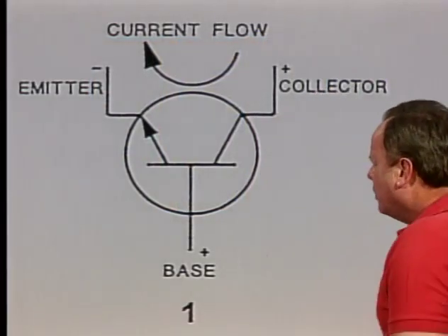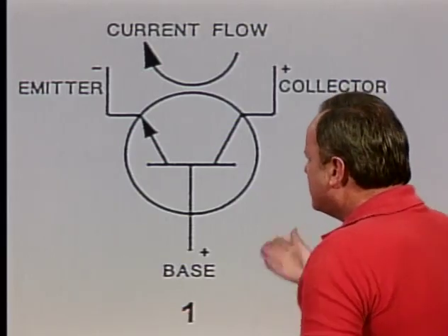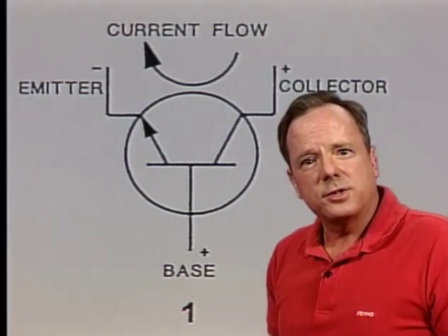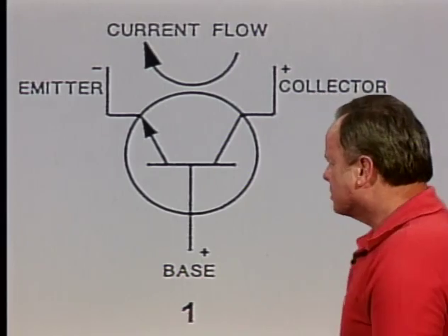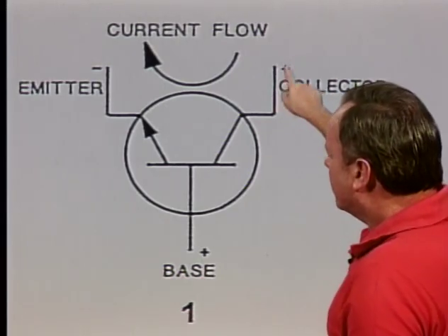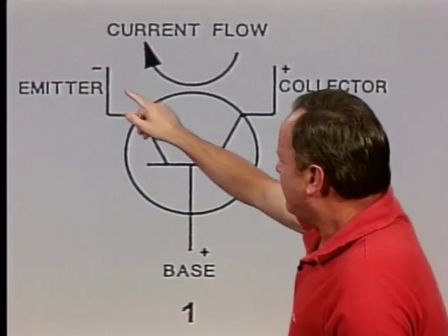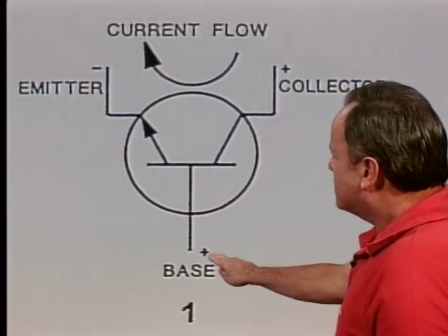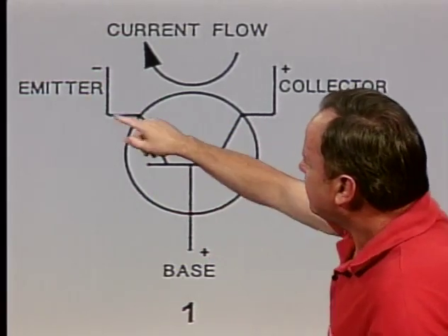And figure 22 is the symbol for a transistor in a schematic drawing. It's a symbol you would use in a schematic drawing for a transistor. And here we have a collector over here, and we have a base, and we have the emitter. Now notice the base is more positive than the emitter, and that's what you have to have in order for